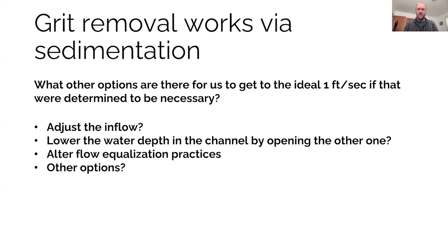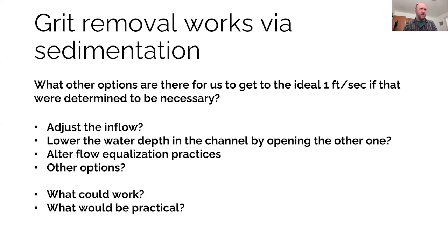So as an operator, you know your system best. What can you adjust? And also what is practical? Of course, you can't adjust everything. But the whole idea behind this and why I went over this math is that there is some math that you can figure out that will give you the best settling of the size of particles that you want. And so if you're not getting very good results from your grit removal system, for example, figure out what you might want to adjust. And then maybe you can improve your removal.